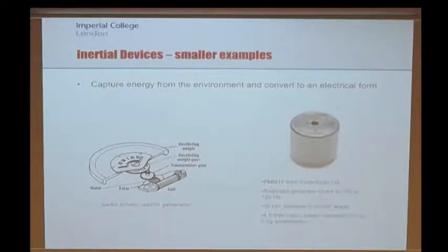In a particular case here for the rail industry, they're looking at monitoring the condition of bearings in rolling stock on the railways. Traditionally that is often done by looking literally at heat coming off the axles on the trains. By the time they get hot though, it's too late, the thing is already failing. So these guys decided they could look at the vibration spectra associated with the bearing, and they decided to power that device with an energy harvester. At that point, they went from purely trying to sell energy harvesters to selling an integrated system that provides somebody with some useful information that happens to be powered by an energy harvester, where the harvester genuinely makes it a better product. That's the direction they've gone in. They're selling services now rather than selling energy harvesters as widgets.